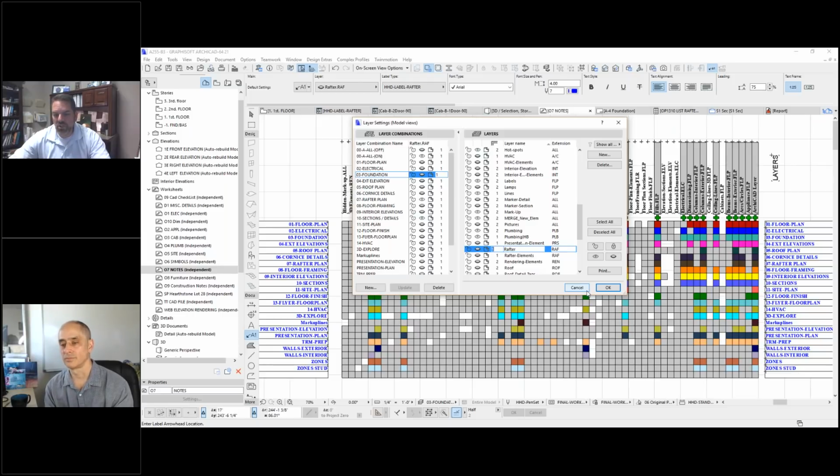Because if you set your worksheet for cabinet layer back in version 18, and then in version 21 you ended up naming it cabinets with an S, then when you started using combination layers that would turn off cabinet layer, it would start messing you up when you place the electrical combination layer on your sheet. Well, by a quick glance, you could see which layer combinations didn't pull over that match the new system.